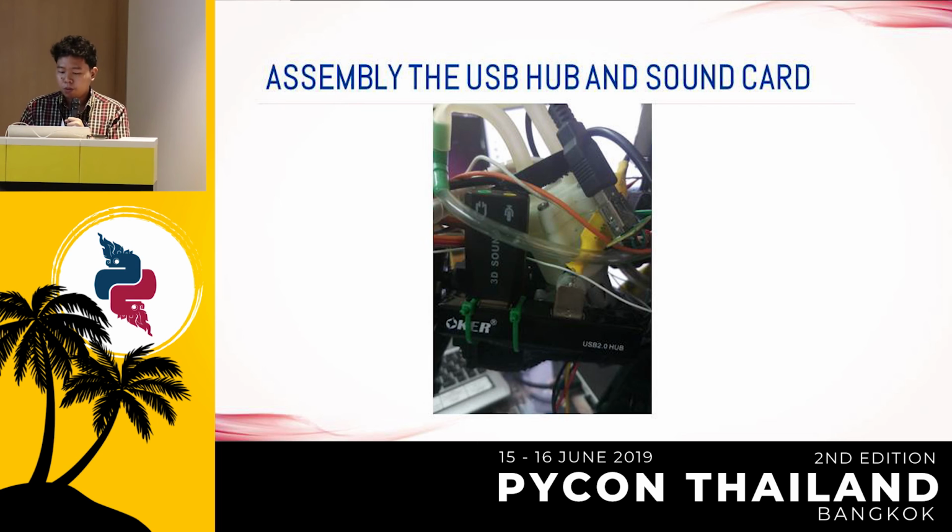That's because the Raspberry Pi Zero comes with GPIO outputs, actually a lot of them, and it does not support audio output or input. So you need something that communicates like a sound card with serial communication. So we're using the USB sound card for this reason, and yes, it's working pretty well. So let's go on to the other one.